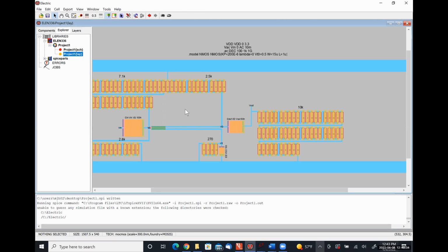So yeah, like another thing real quick here, my transistor here isn't 50 over 3 1/3 because in your layout, you need to use integer numbers for integer multiples of your scale factor. So 2 possible options would be to make it a 45 over 3 or a 60 over 4. Both of these are going to be close to 15 microns over 1 micron.